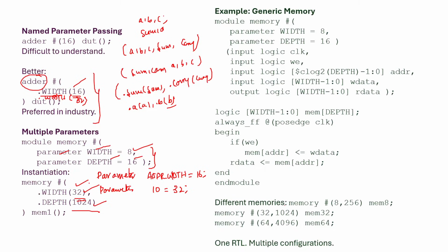So how the FIFO depth and width we are writing. Just simple basic read and write operations I am doing here. Some generic memory module. Parameters: width is 8 bit and depth is 16. I am just taking the clock and enable pin.